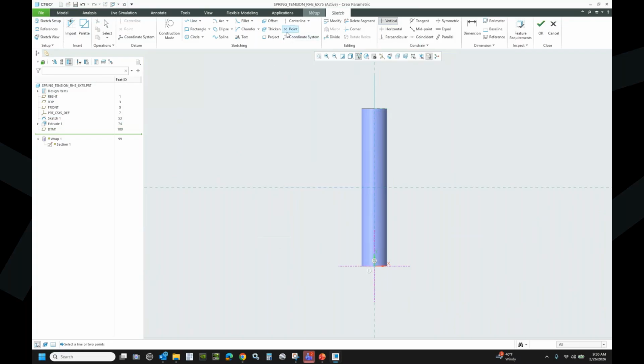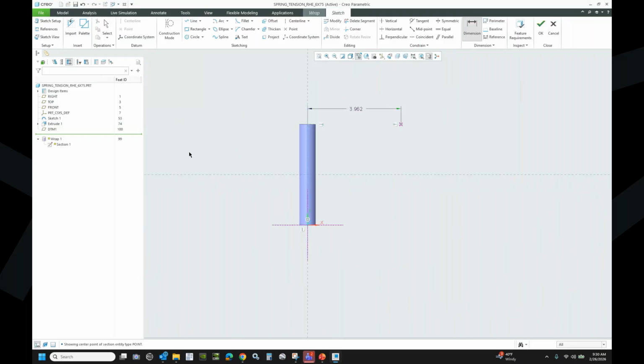Well, this coordinate system represents your thumb in that, and then we're going to create the rest of the sticker here. Now I'm going to create a construction point that's kind of in line with this, and I'm going to create it out here, right? And then I'm going to give this dimension from the center line to that point. And we're going to use that in a relation in just a moment. Okay, and then what we're going to do is we're going to create the geometry that represents the rest of this coil. And we're going to include that little transition at each end. And that's why I made this a 1/4 of an inch longer, because we're going to need to consume that space. So I'm going to start by creating an arc.